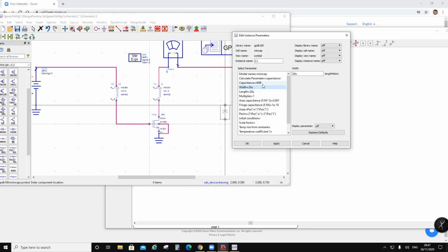Okay, so this is like 0.4 picofarad and 30 would be the maximum size this PDK is allowing you on a capacitor. So that's 900. Okay, so the issue using large capacitors or inductors is that you have to make sure that they are not resonating or anti-resonating. Okay, so I'm going to use this size.